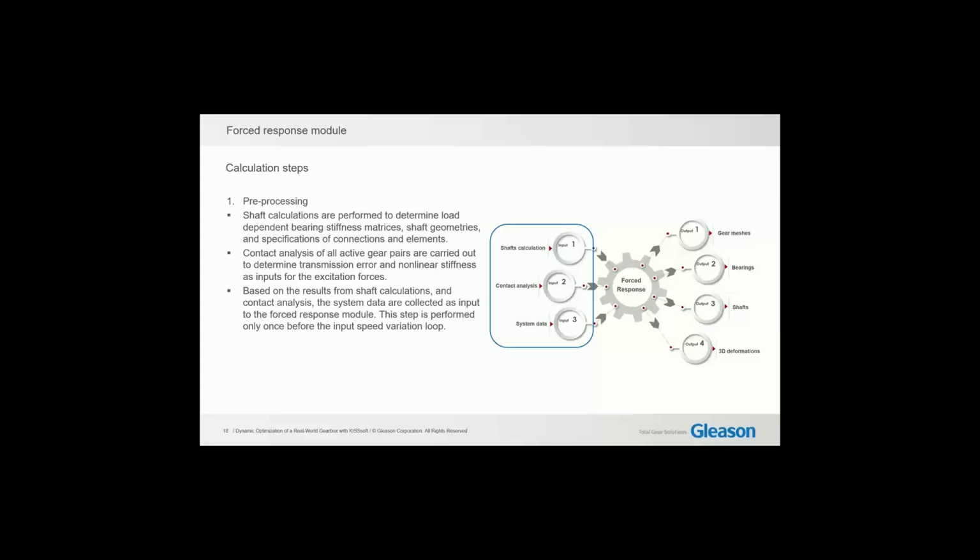This step is performed only once. So if you change any setting which is not directly related to the shaft or contact analysis, force response will not use this step again, just to save time and speed up the calculation process.